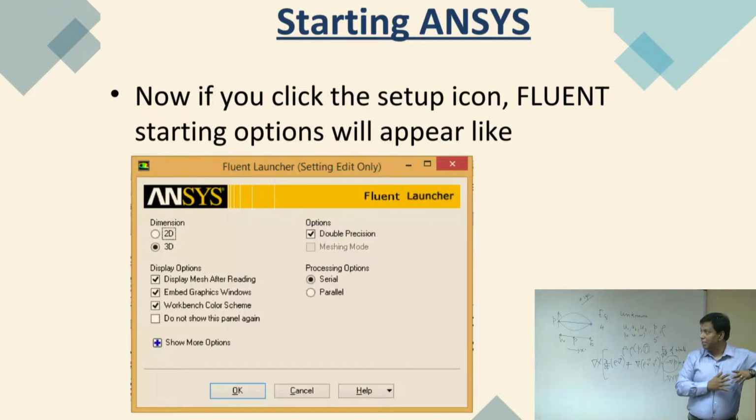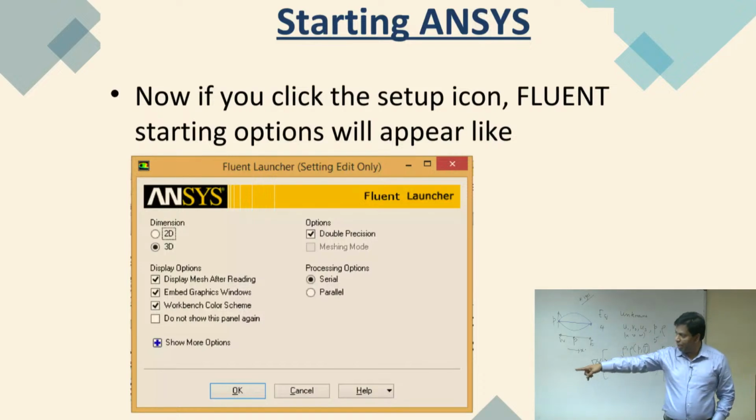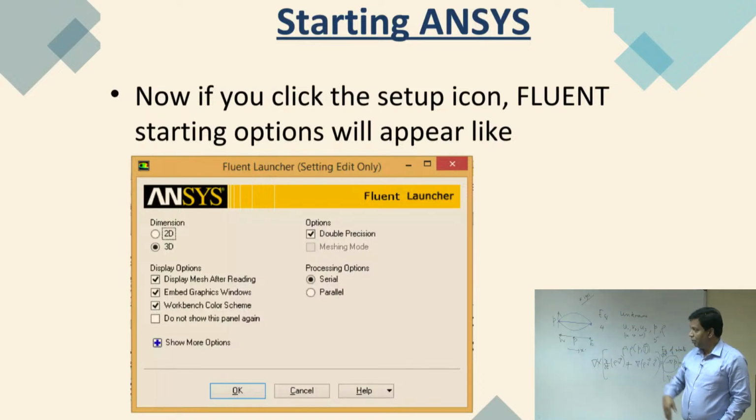Okay. So, 32 is huge, and it takes a lot of space; the data file will be very big. But generally I use this one because that will give you more accurate results, but it takes a lot of your space, the file will be bigger. And now what you want to display here, displays the mesh after reading. So, when you give OK, that it can read your mesh file, and you can show which one you want, just tick here.